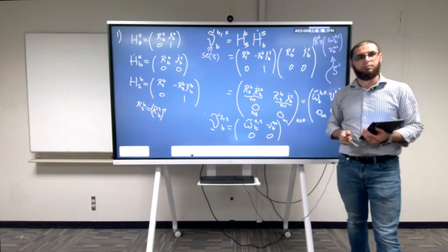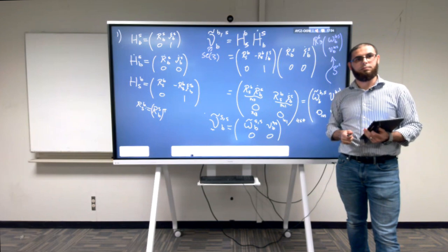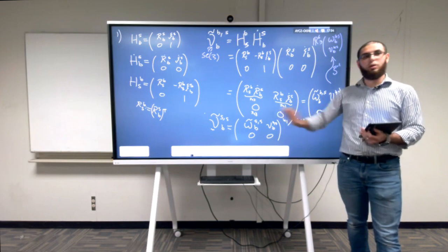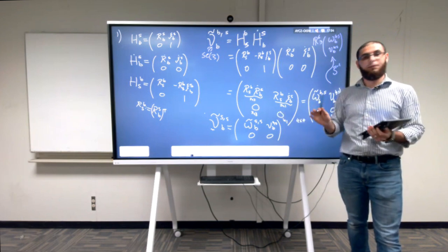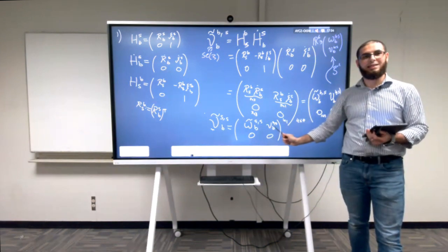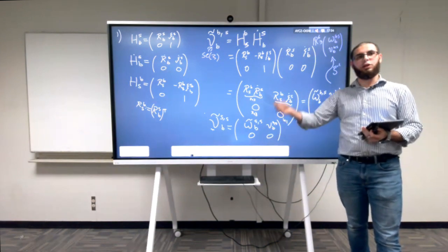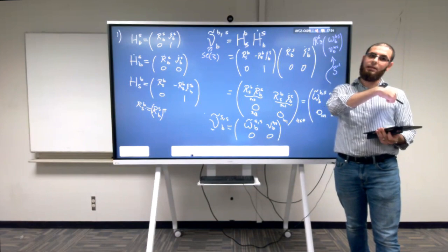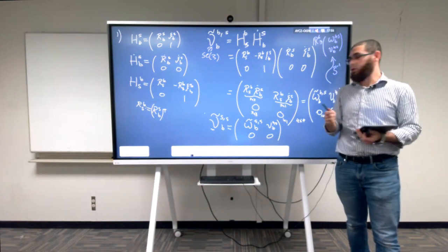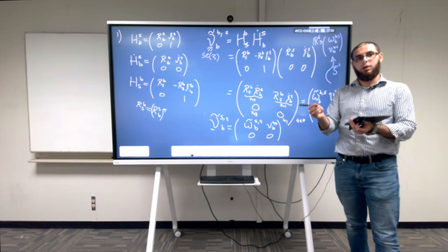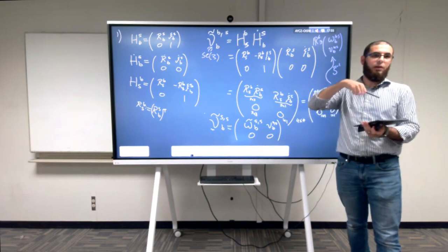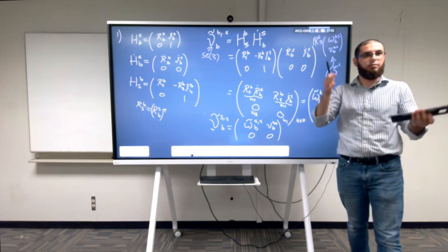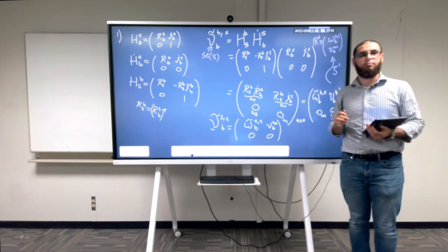Assuming the frames are moving relative to each other, just follow the math. Follow the math blindly, and you find that this guy, which is the linear velocity of frame B with respect to frame S, as seen from frame S, expressed in frame S, is equal to the rate of change of the origin of frame B with respect to S, just divided by time, right? Let me know. Question.